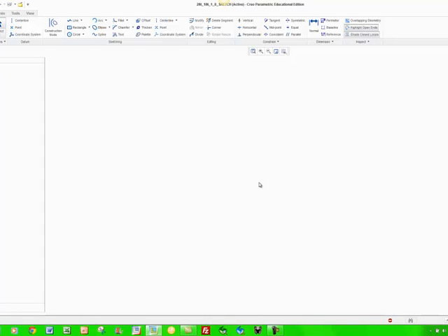Alright, so just a blank screen right now, but you'll see up here you have been prompted with several different tools that you can use. Right now we're going to start with inputting center lines. Center lines create a 2-point geometry, center line is what it says. You're going to click, and you'll see as soon as I click, a center line will project all the way up around the screen, and I can move it around. I can place it horizontal, vertical. I'm going to put this one vertical.